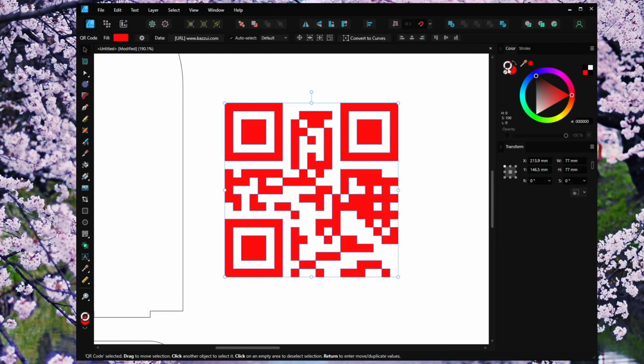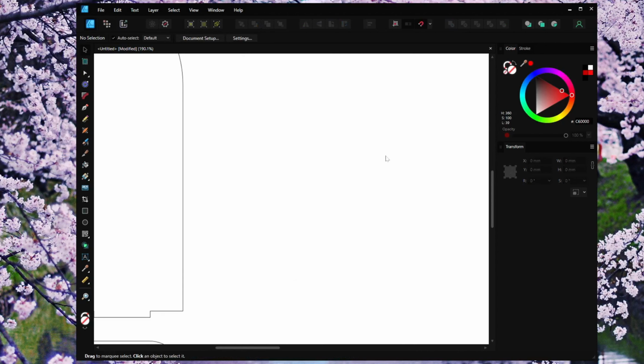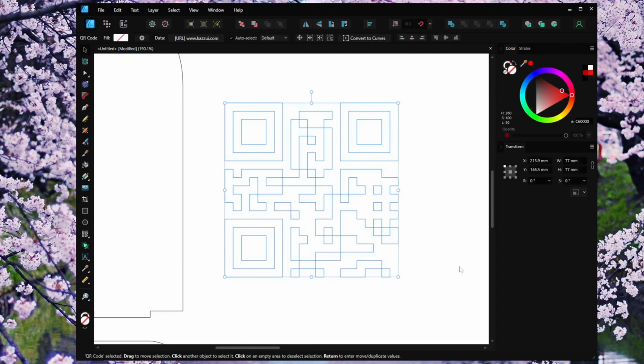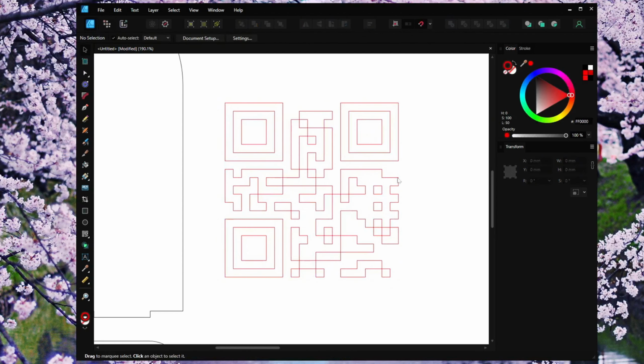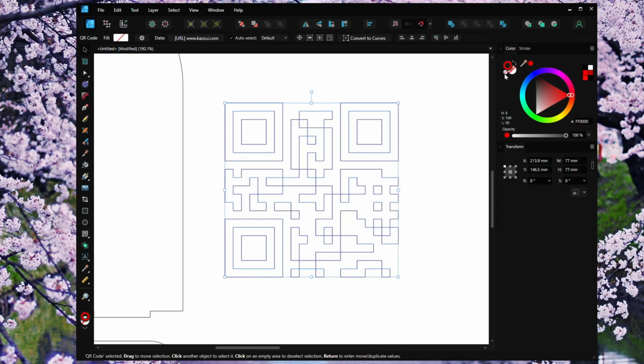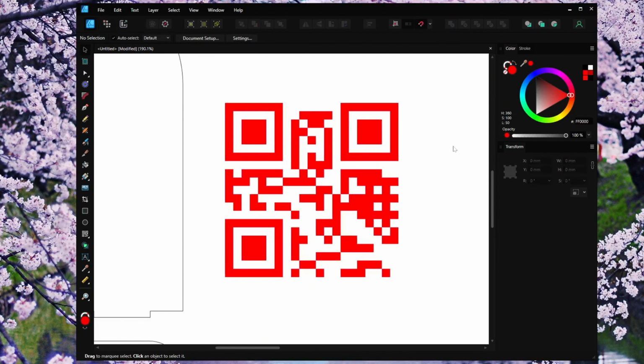So these are very helpful. You can use this one here to choose the fill color. Or you can also click on Set Fill to None, which makes it invisible. It's still here. And then you can go over to Stroke. So you switch between them by selecting them. So click on Stroke and now you can select the stroke color. But as I said before, in this case, we don't want the stroke, so click on None, and then change over to Fill, and choose a fill color again, and that is it.